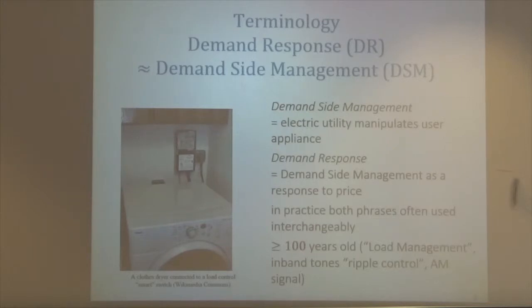So other countries like France don't do that because they have other ways of controlling it. And one of the ways is, in particular, to adapt the usage to force, for example, all the boilers and a number of appliances to work at night when there is much less demand. And nuclear plants typically go together with pump hydro, where you pump at night also into some lakes.